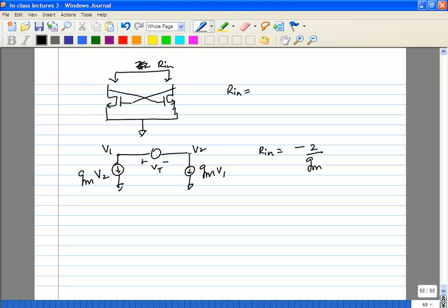Okay. Now what that means is, so now you know how to design. If you have a certain resistance of the tank, remember we looked at the one port view last week. That is, if the tank has a certain resistance Rp, you know that the negative resistance for oscillations should be equal, but for reliable startup you want it to be maybe a few times that, right? Loop gain of 1 is the condition, but you want a little bit higher, maybe loop gain of 2 or 3 for startup. Okay. So you will correspondingly design your GM. So obviously, if you remember, we talked about this. If the parallel resistance is smaller, that means you have higher loop gain. Remember that from last class? Kind of. Not sure. Okay.